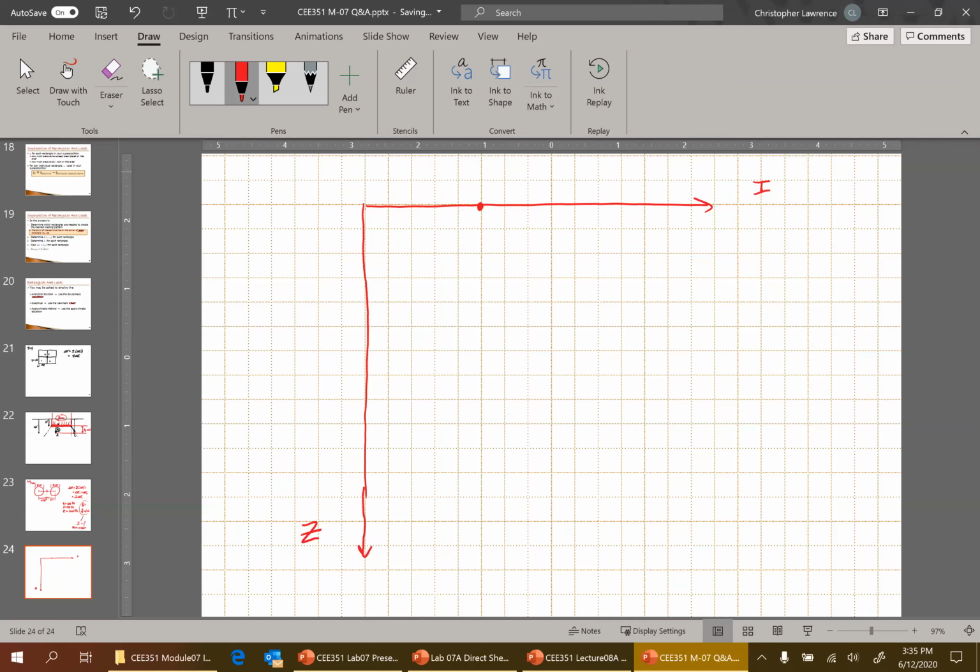When you get Z equals 0, you actually have an influence factor of 100%. Sigma, the induced stress, equals Q. Influence equals 100%. So we actually see something like this, 1.0, and you get that right there, if they're the same Q and you're talking about a point directly below the load. Then you see the square if I plot it with depth.